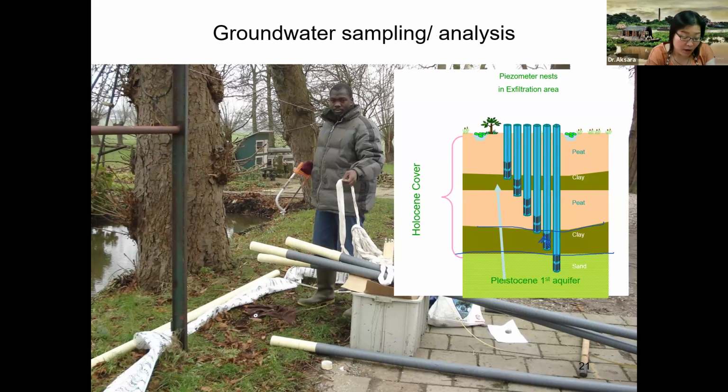Okay. So since these nested monitoring wells did not really reach the same aquifer, what you are expecting in each piezometric well must be different. What I'm saying is that the piezometric head in each aquifer is not supposed to be the same.